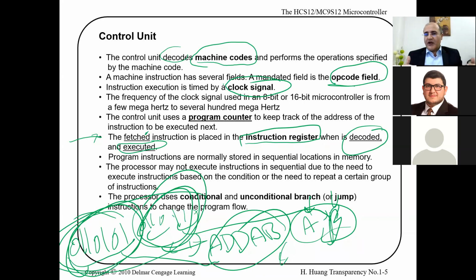Today we're in the gigahertz range in computers in general. But in the microcontrollers area, we are in general dealing with 8-bit and 16-bit microcontrollers, the most common ones. We're in the range from kilohertz to megahertz, usually megahertz. For example, our microcontroller, the HCS12, we are able to configure it to work depending on the crystal. There is a crystal, an 8 megahertz or 16 megahertz crystal. We're going to talk about it later.